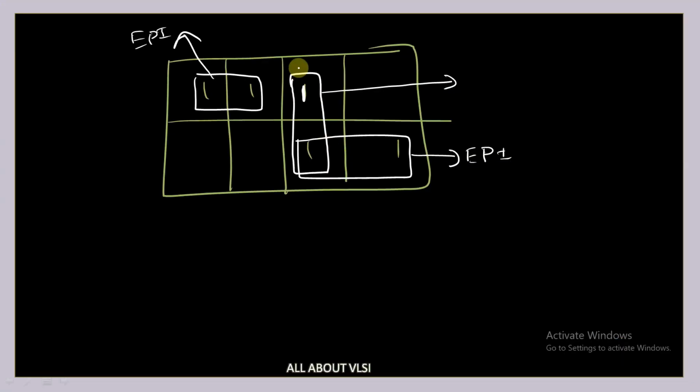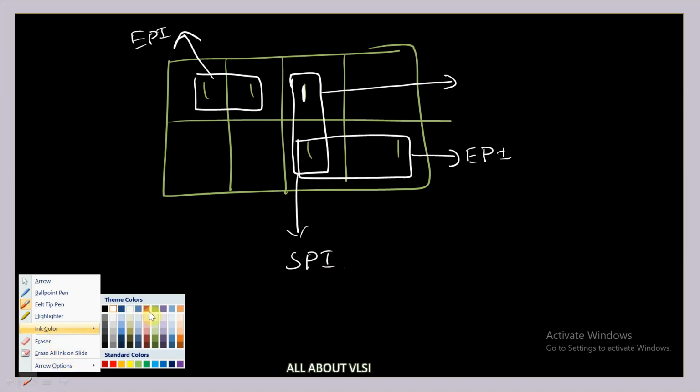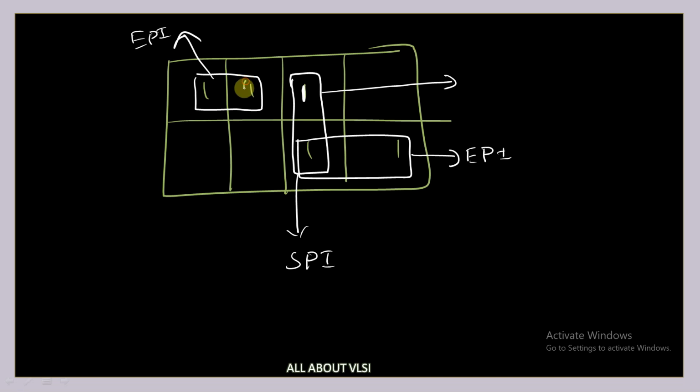No, because this was a selective one. This is a selection, right? So you can also make this group. Okay, so this is SPI. Now there is one more prime implicant possible, that is this one. There is one more prime implicant which is possible, that is this particular group in the dotted lines. Now whether this group is RPI or whether this is SPI. Is this an SPI or an RPI?